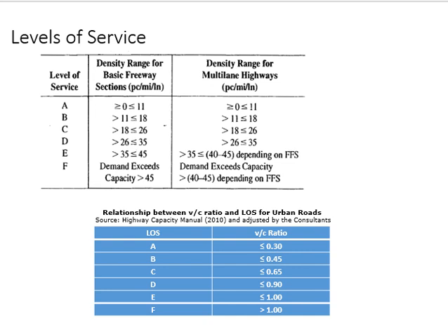Flow rate upon capacity. So if your flow rate upon capacity is between 0 and 0.3, your level of service is A. If it is more than 0.3 up to 0.45, it is B, and so on. But I did not find this type of table in the manual. This is from somebody from the industry.